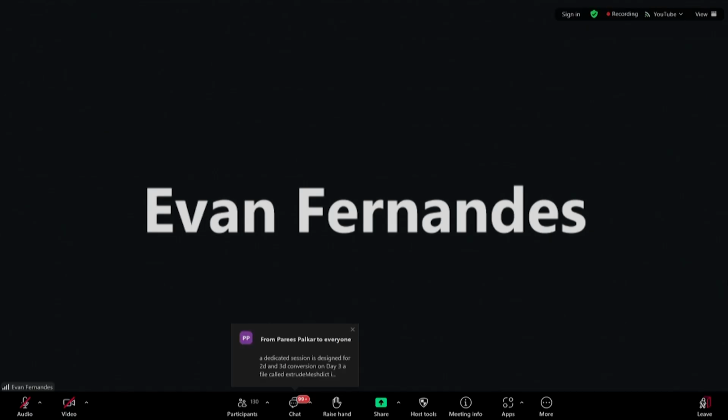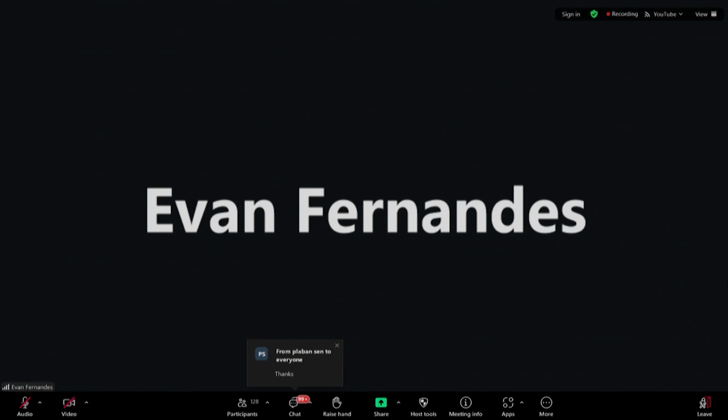What solver is suitable for metal or polymer erosion? For polymer erosion, we haven't really tried any of those. Wait, just let me have a look. Erosion related, right? So you can try using one of the Lagrangian solvers because as Mr. Advait Gupta also said, they tried and they have used some of the modified Lagrangian approaches. So you can try using one of them depending on the case you want to solve, because we haven't really gone too much in detail about erosion and additive manufacturing as a whole.